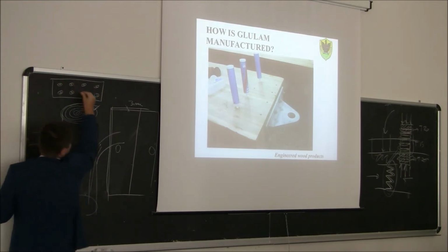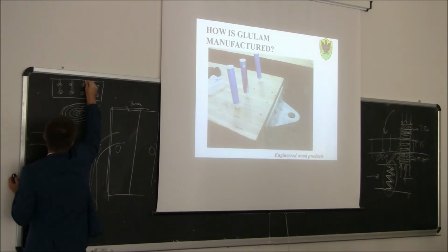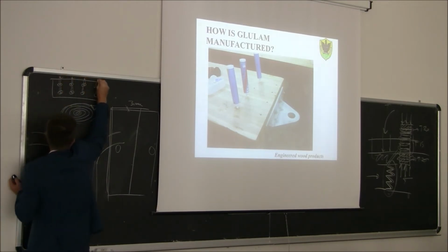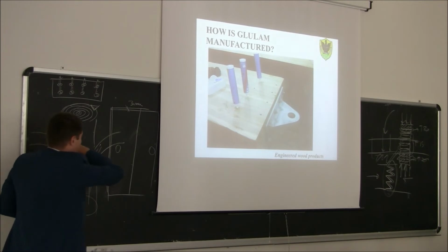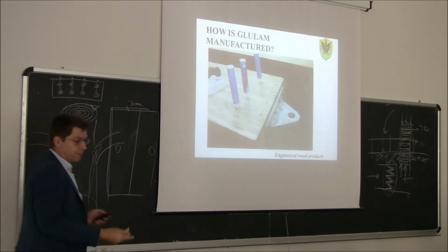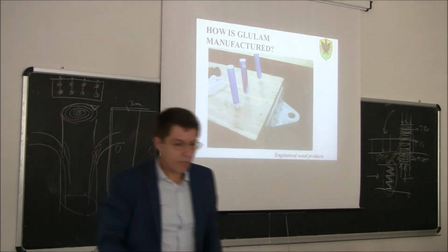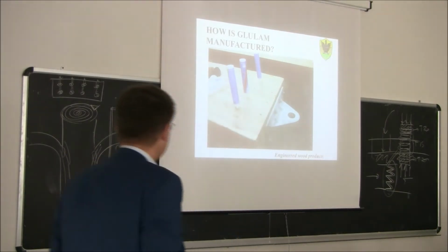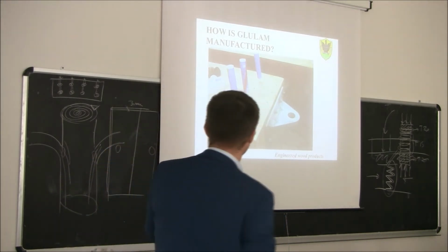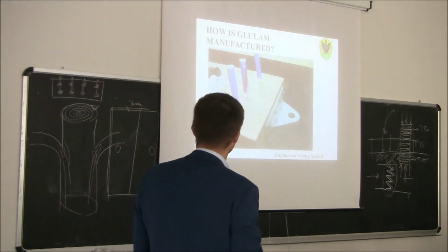And from here you have some vertical holes, where you inject the epoxy resin. So the epoxy resin is going to fill this gap here and glue the threaded rod to the wood. We will discuss later on how to design this kind of connection here.